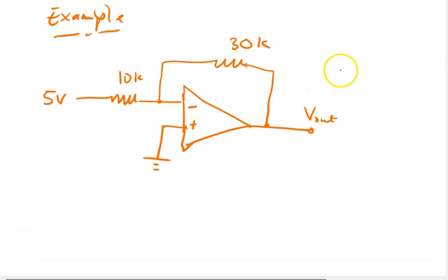Okay. So with this one, how does it look? It looks like an inverting op-amp, where the input voltage and the resistor are connected towards the negative side. So the general formula is given by: A is equal to V out or V naught. This is the same as V out.